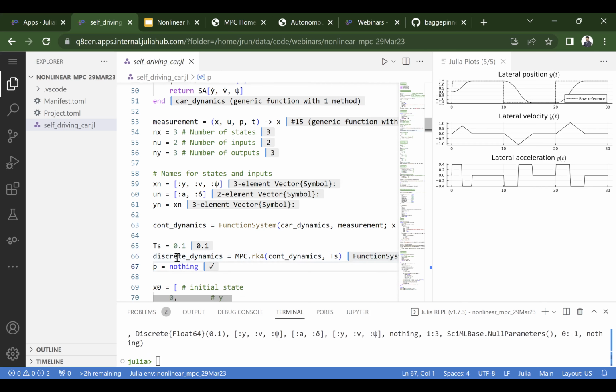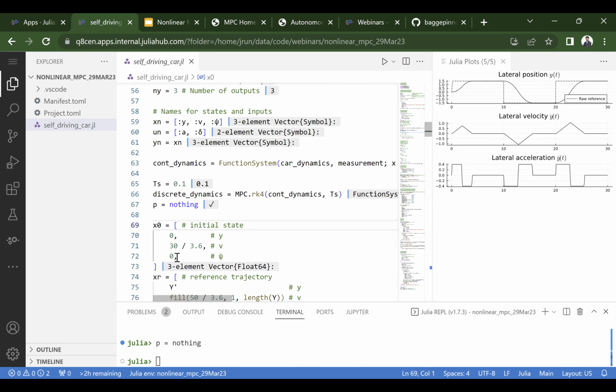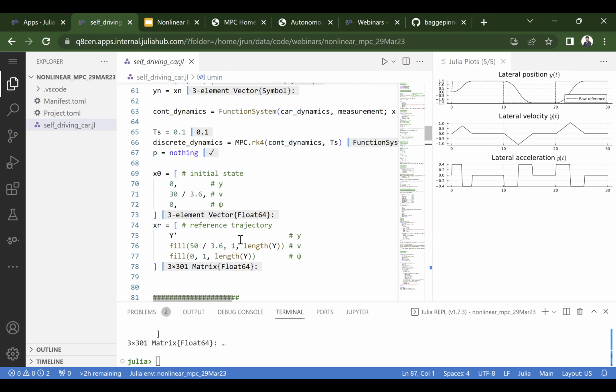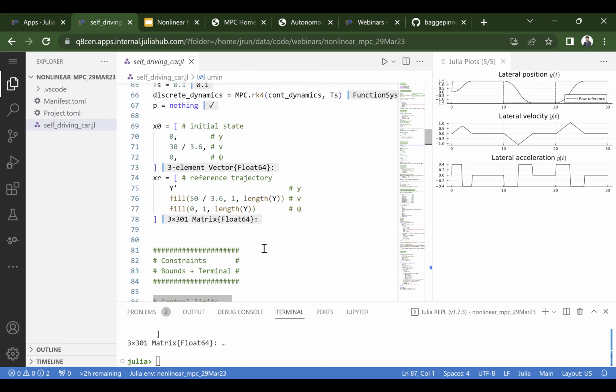And really what we're designing the controller to do is figure out, via an optimization process, what control signals need to be fed into the system every 0.1 seconds, right? So that's the regime we're operating in. Next, the set of bookkeeping is to design the initial condition of the system and the initial condition of the reference trajectory. Again, this is just some bookkeeping that we've done.